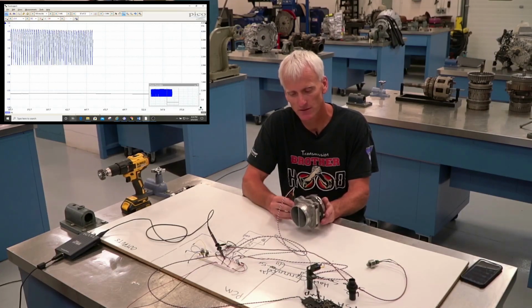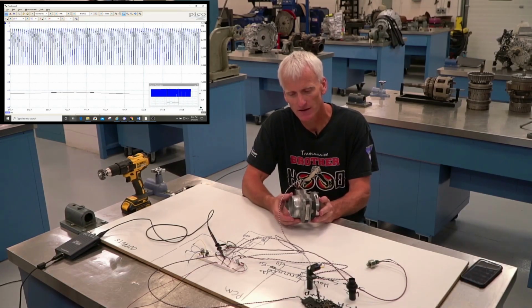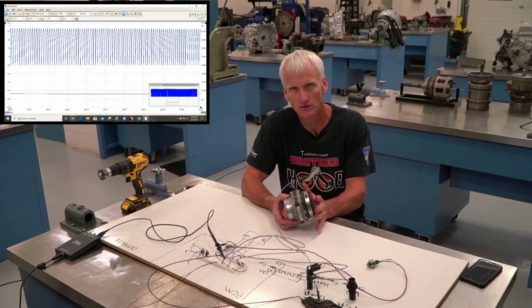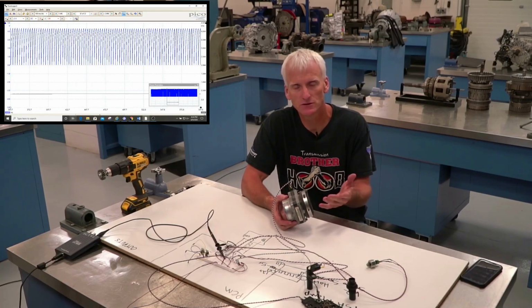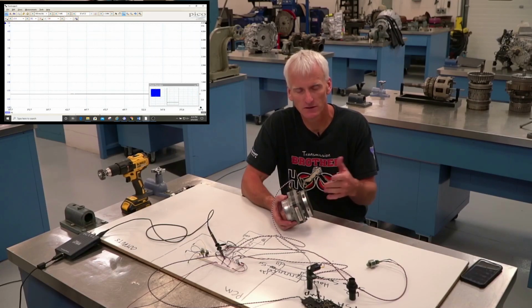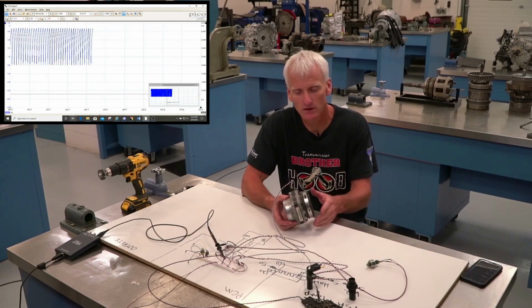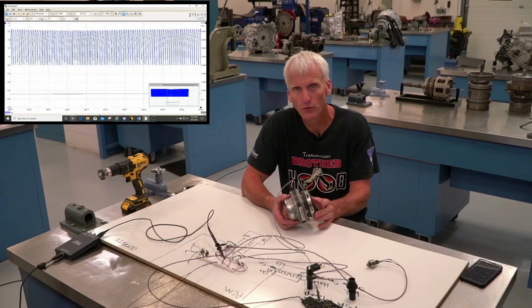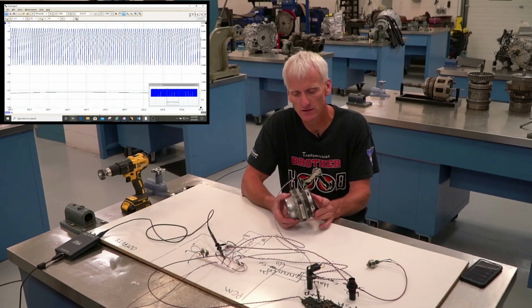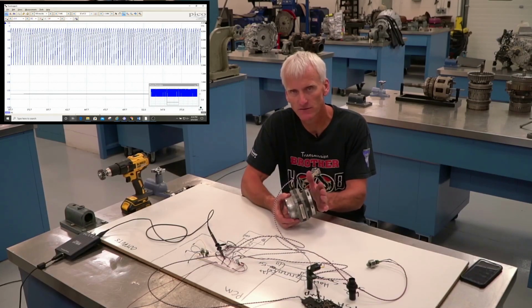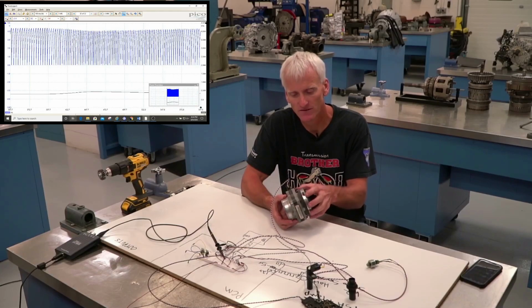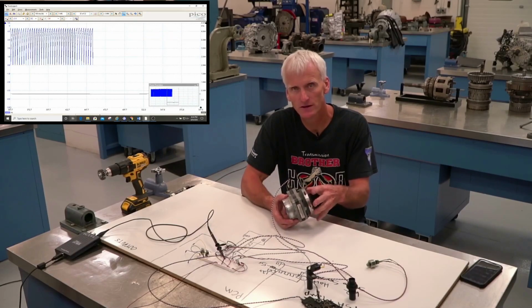That's how the GM mass airflow sensor operates. And the computer is going to use engine load to determine what pressures it needs to run the transmission in, how hard to shift a clutch, so that way it's not slipping too long. So load is a very important input to the transmission function. A mass airflow sensor is a very common device to measure or determine engine load.